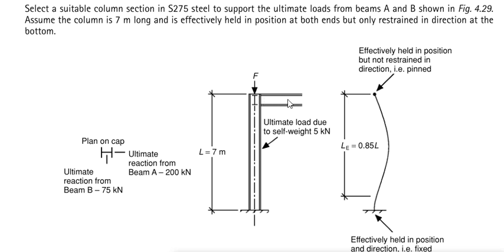So your beam applied this way, once it's connected here, you give an offset of 100 millimeters from the face of the column. So what it means is that for this column you have 100 millimeters from the face, and then you're going to take the depth of your column, divide it by 2 and add it to the 100, and that will be your eccentricity in this direction.